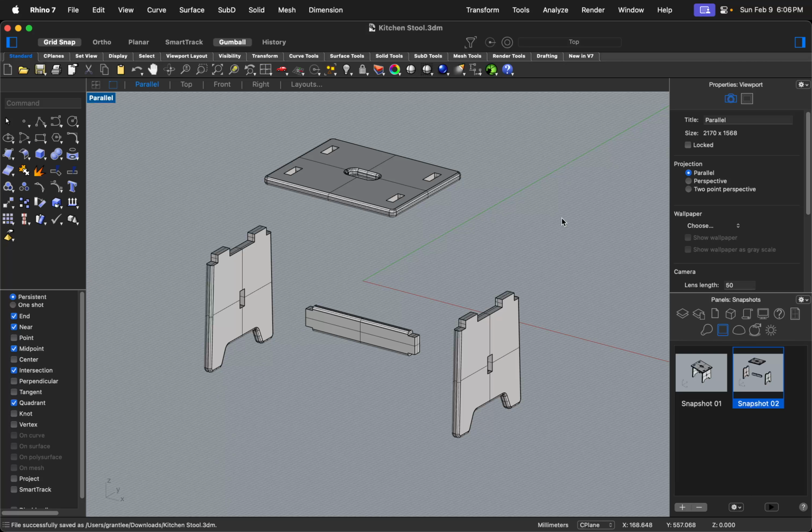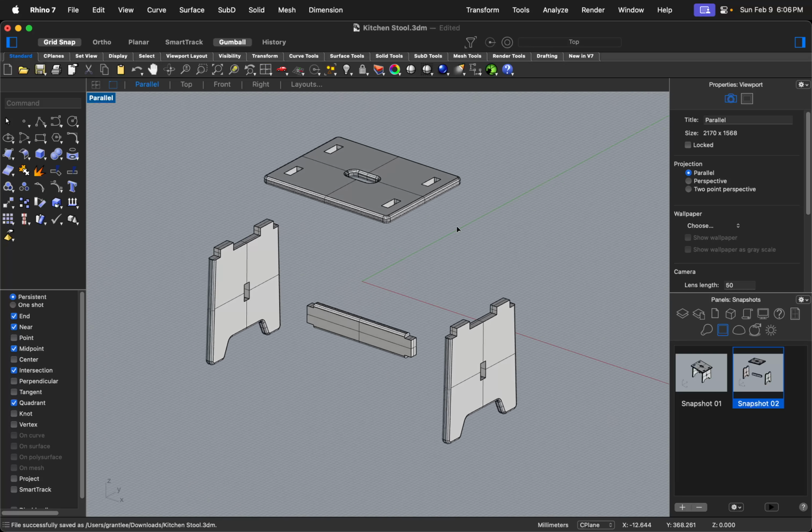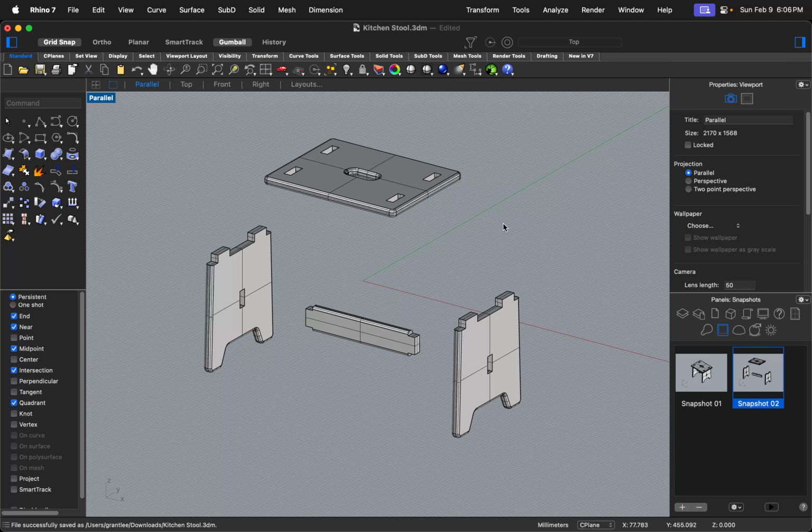The snapshot allows you to restore the condition of your 3D CAD model. For example, if I double click this one, it will do assembly work for me, and you go back to a particular angle. And if I click the extruded one, it just opens up. And no matter where I click, we always go back to the particular angle, and all the conditions work well for me. You can even do like a staggered joint. For example, I can go back here, and I will move this up 200.